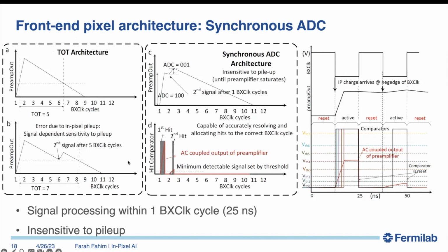Then, of course, it also has the added advantage regarding in-pixel pileup. Not so much due to signals coming in every 25 nanoseconds, where the probability is fairly low. But say there are overlapping clusters, and you see small charges from an adjacent overlapping cluster within the same pixel, then there's no way to decouple whether you're looking at 2 signals or a single signal. Whereas in our approach, we are AC coupled between the preamplifier and the ADC, and because of that, we can correctly resolve the 2 hits, so we are pileup immune.